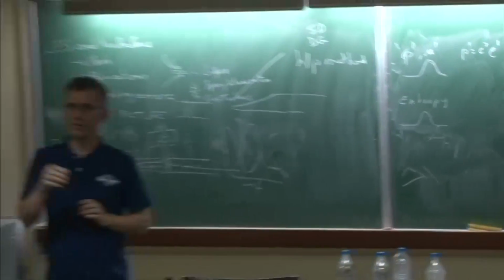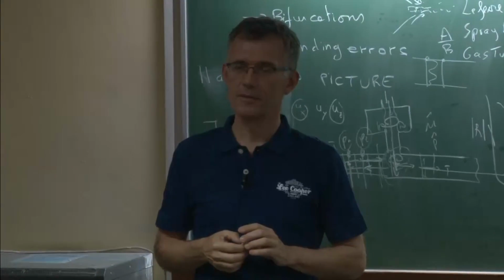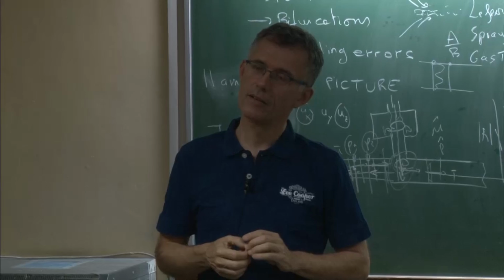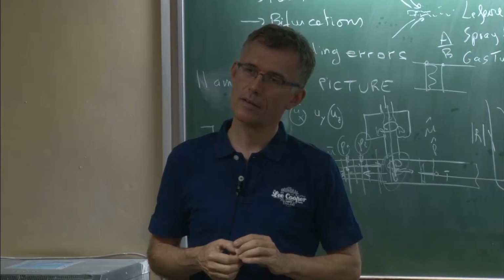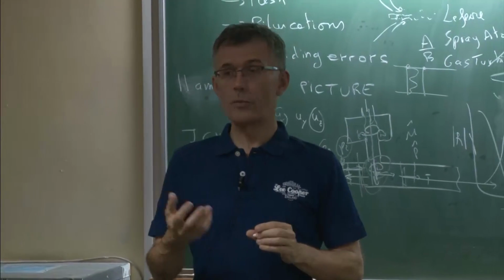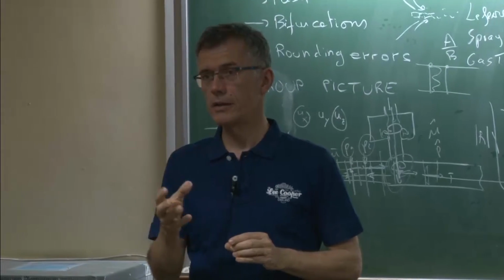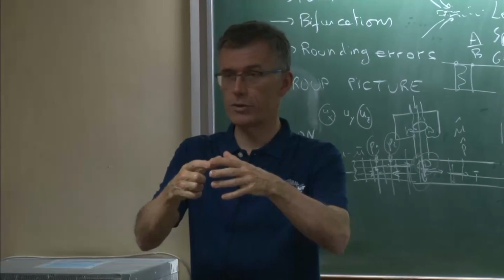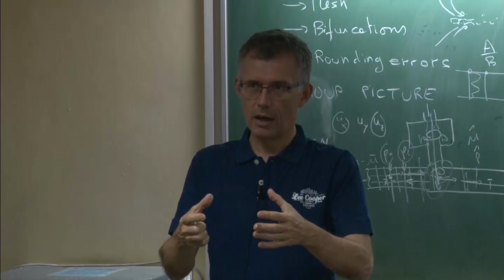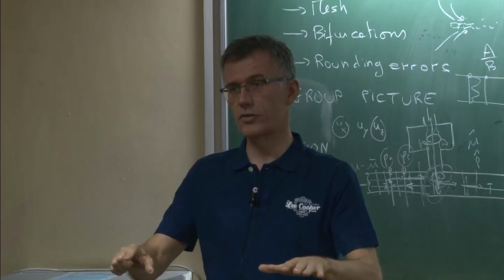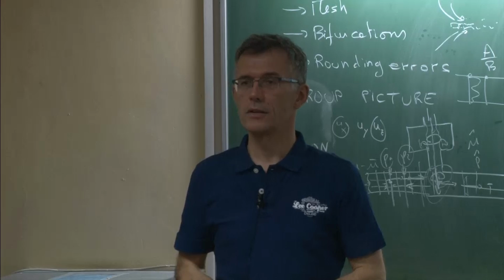I'm not sure if that answers your question. Can we experience entropy waves just like pressure waves? Sure, an entropy wave is just a hot spot. If you have a zone where you have a high temperature locally with a low density, so that the pressure is constant, that's an entropy wave.